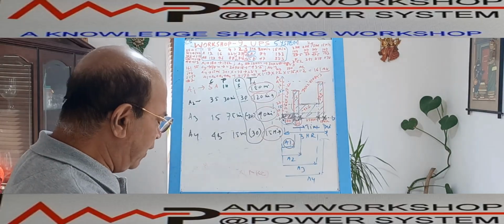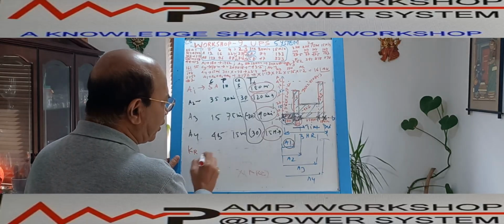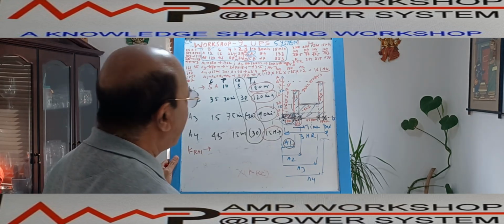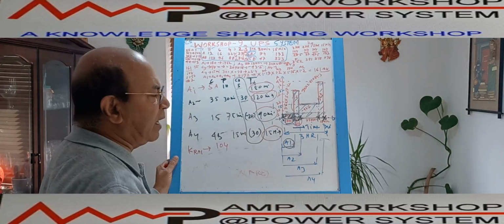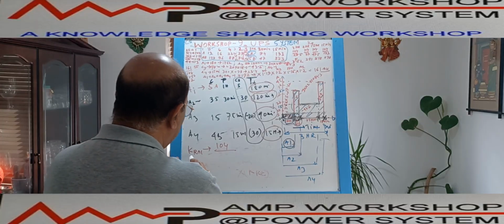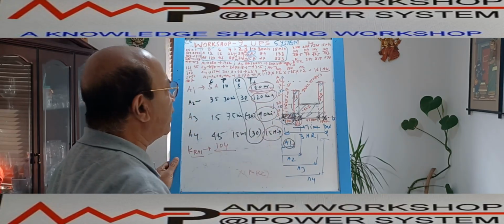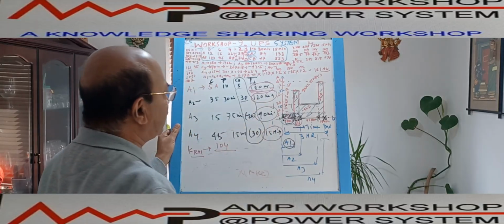Suppose the discharge factor is KR A1. We have already said the rated ampere hour of the battery, that means the C8 capacity of the battery, divided by the current it can discharge for the total time of the A1 section. So 180 minutes means 3 hours.